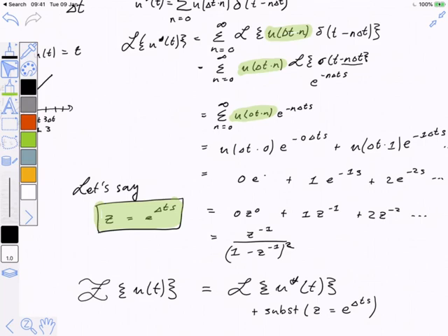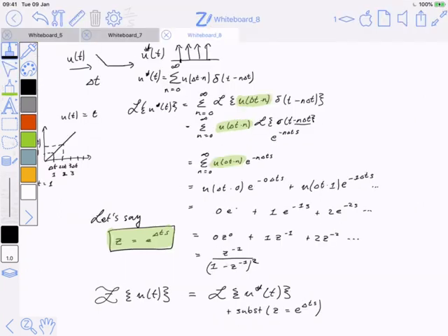And so there is no single unique function of time that goes through the points at the sampling intervals because of aliasing. The best you can do to invert the Z transform is to give me the function values at the times of sampling. Now that you can do exactly, but you can never get back the actual function of time. You can only ever get back the values at the sampling interval.